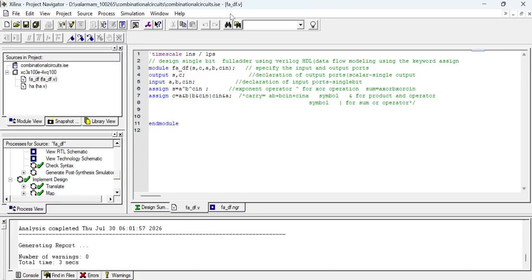Simulation is nothing but verifying your design by giving proper inputs to validate your output, whether it works or not. For that, in Verilog HDL, you can write a .v test bench file also. You can simulate all possible test vectors and validate the output. So write a test bench to validate your design. For that, first we'll discuss the half adder.